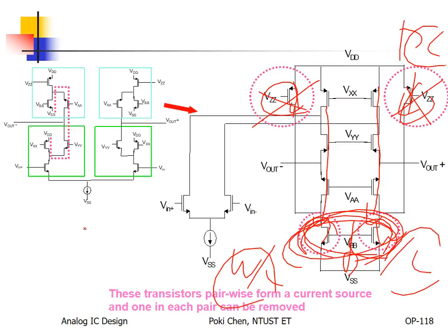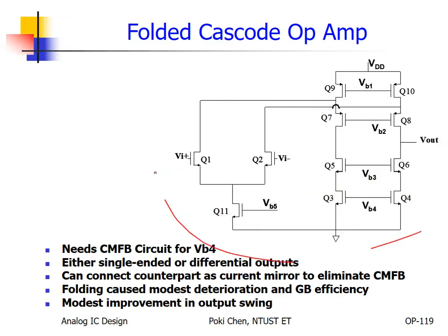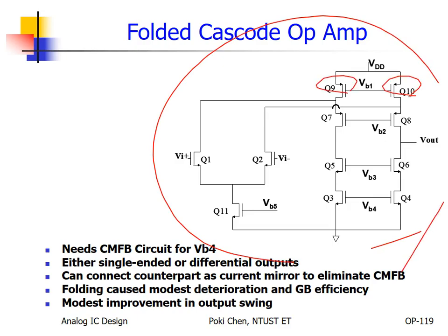If you get a good enough concept, then a similar issue happens here. Those two are helpers to redirect the output differential AC current, which all the way flows through Q7 and Q8. They are cascode transistors, with one output here and the other output there.